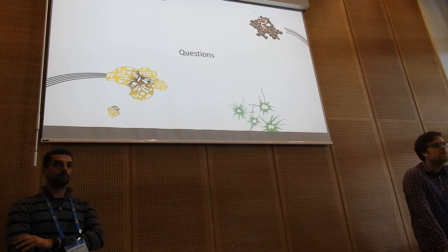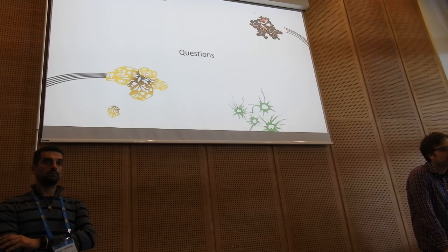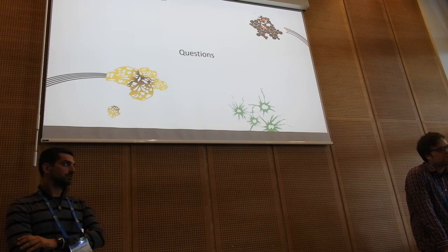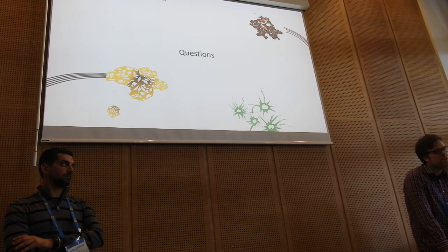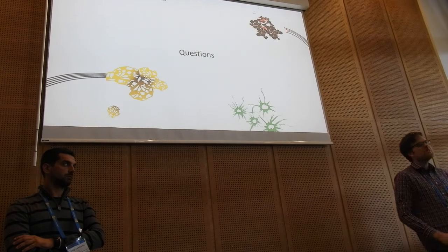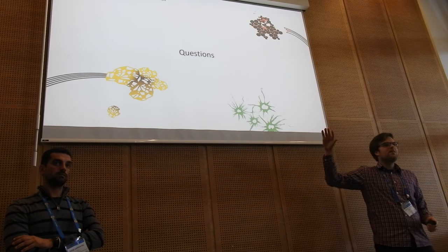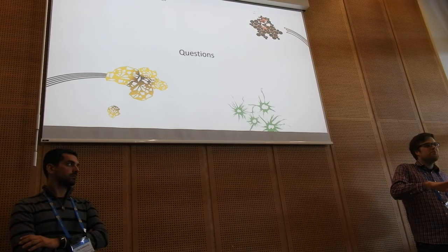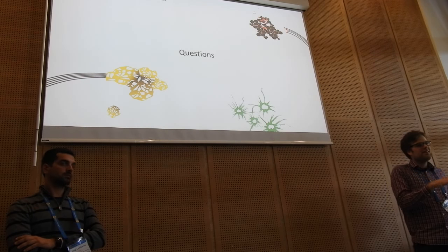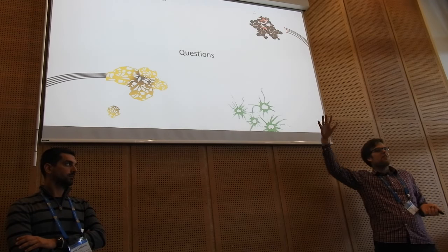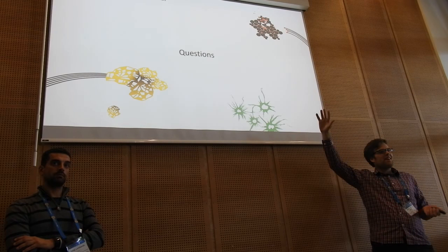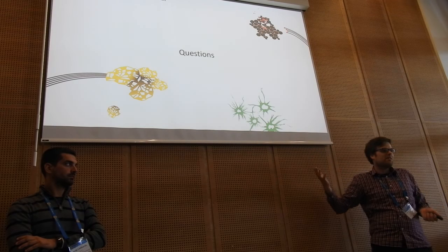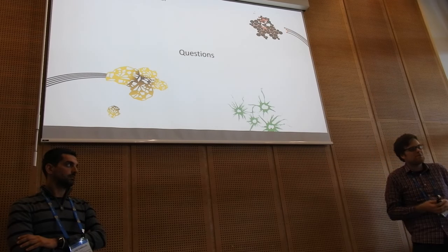Did you do some sensitivity analysis? Which parameter affects your outcome the most? Yeah, it's not in the paper, but what we found mostly was that soil depth was very uncertain, particularly the spatial patterns. If you take a homogeneous soil depth throughout a slope, that doesn't work well because your bottom areas are way too stable. Typically, soil tends to accumulate there. Your top areas are way too unstable because at those very steep areas on the high end, it doesn't have the capacity to carry that much soil.